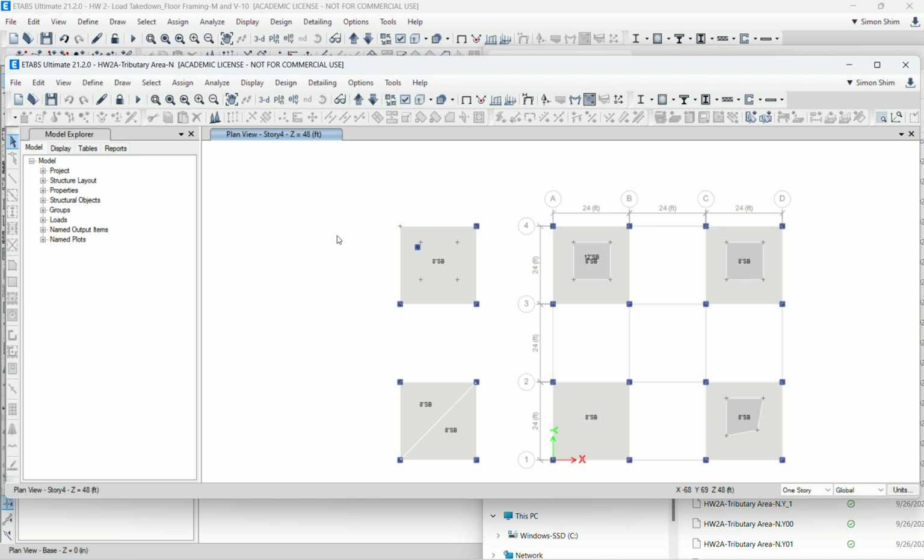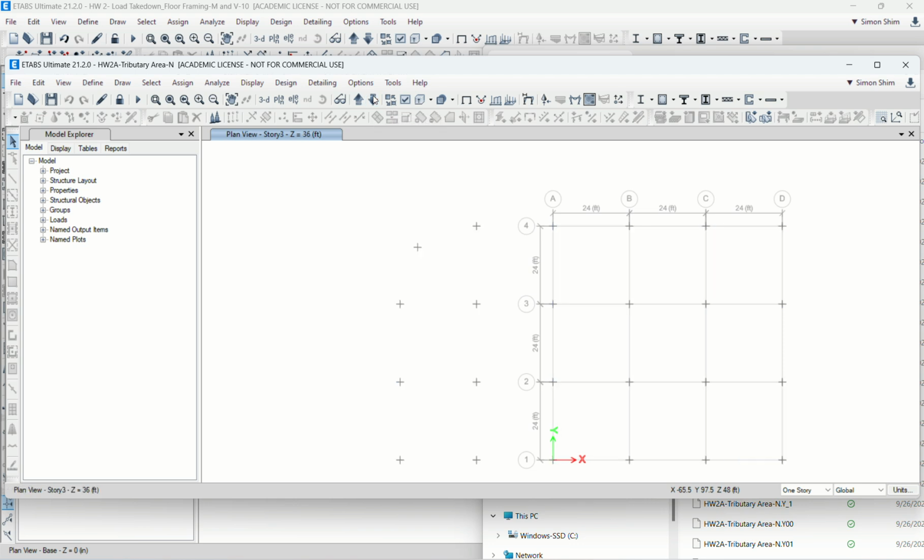So now we're going to check the reactions, the column reaction. I think ETABS is more building oriented. I'm going to click this arrow button to go down. You can just go up and down along the floors. So I click go down, so this is the bottom of the column. What I want to do is check this reaction based upon 1 PSF of uniform load.